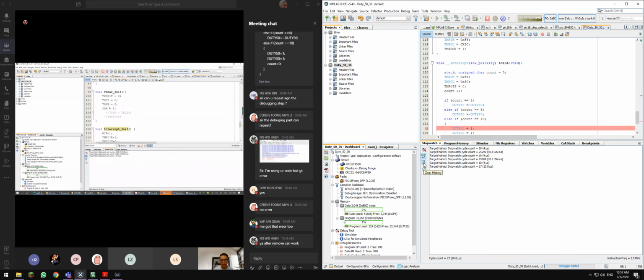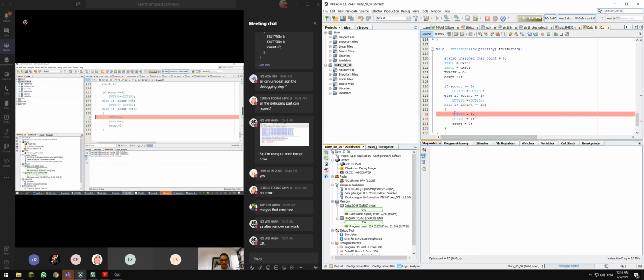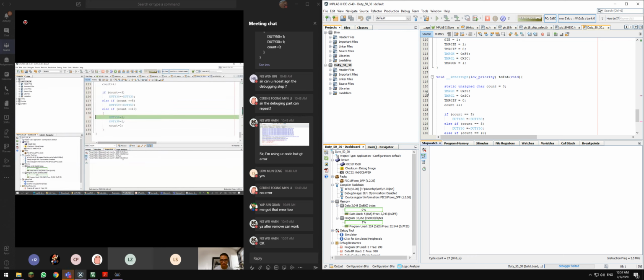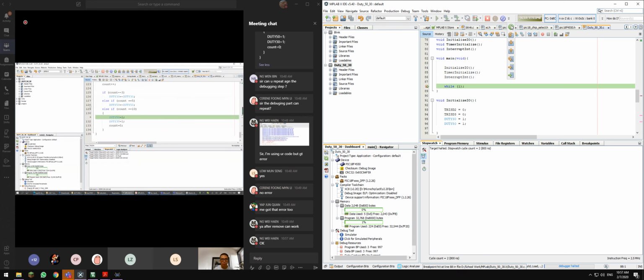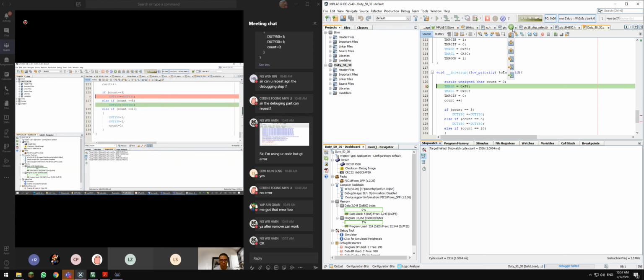Okay, you press reset. When I directly see 10 milliseconds, come here. So it's coming in about 10 milliseconds. Okay, so I press reset. I put 5 milliseconds here. It should come in about 5 milliseconds. Class, it is impossible to get exactly 5 milliseconds, because there is interrupt service routine latency. You know, all these things are calculated. I put it over here, I reset the system, it's about 3 milliseconds. So every 3 milliseconds it toggles.